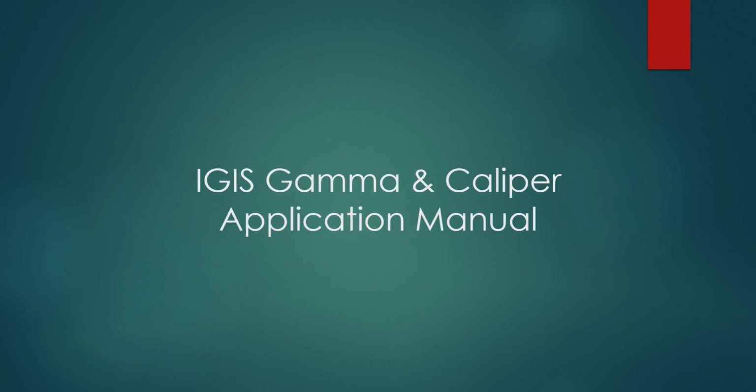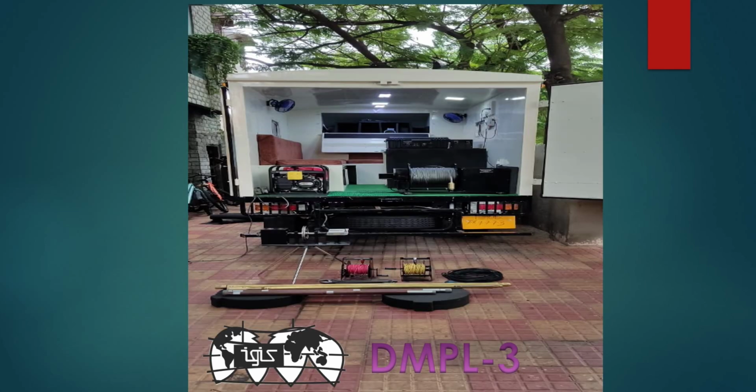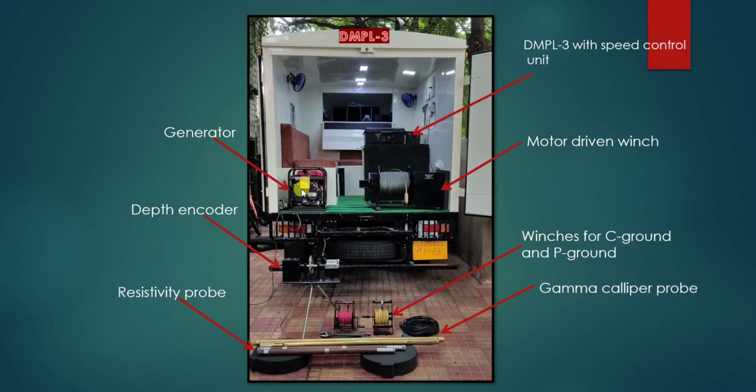Let us now discuss the gamma and caliper log applications. This is the basic setup of the DMPL3. This is a gamma cum resistivity caliper borehole logger. If you see the components here, there is a generator for the power supply, and the depth encoder, which is used to find how deep we are going. And these are the resistivity probes, in which you get the resistance and self potential, short normal, long normal, and lateral.